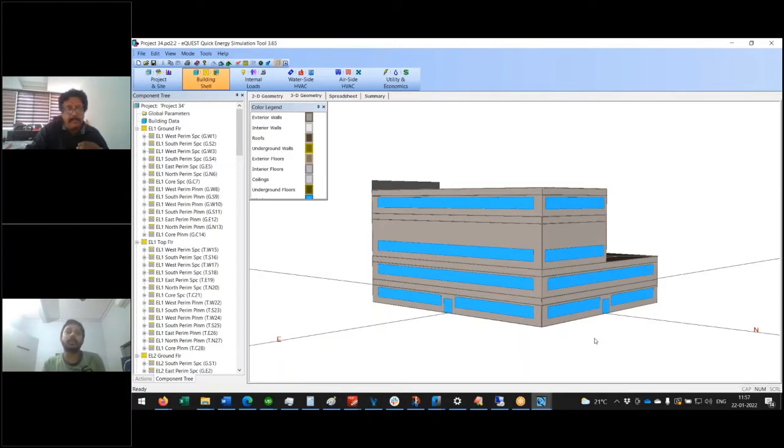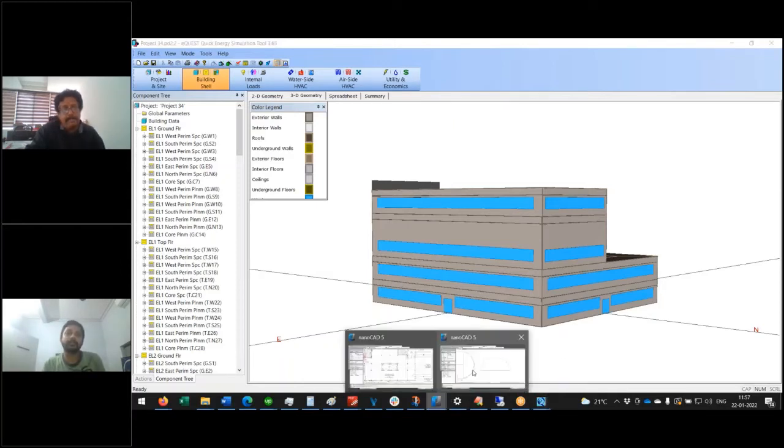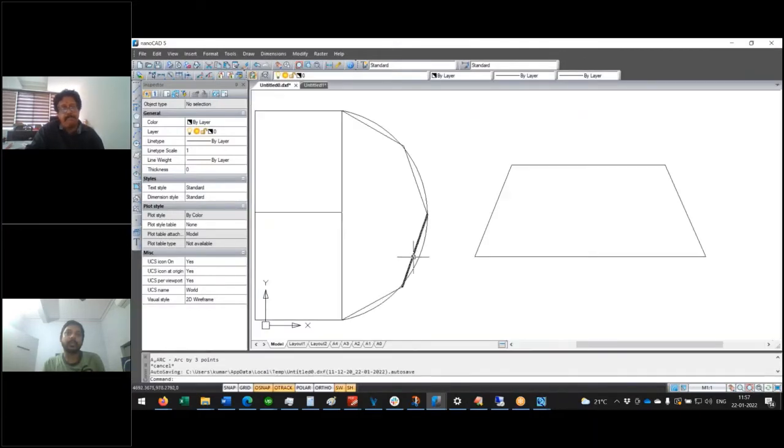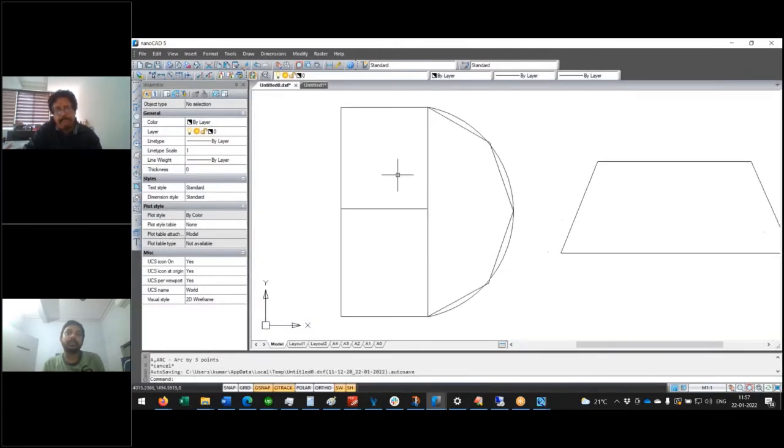Right. Okay. So in case of an atrium project, let's say these two are your rooms and this is the balcony. Is that what you want to understand? Similar, right? So these two are the rooms, and then you have this balcony. If it is not covered, it's just a balcony open to air, there's nothing over here, then this should be modeled as a shade and not as a room.